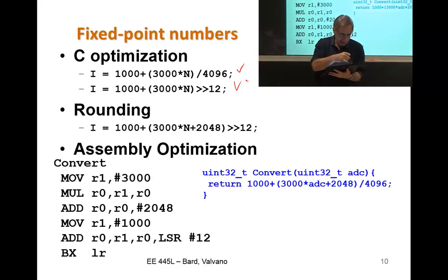Do you have to program in assembly language in this class? No. But we're going to look at assembly language in a couple of places. We're going to look at it for the issue of overflow, because it's not in C that the overflow happens. The overflow happens in assembly, so we'll make sure that when it multiplies, it's really doing a 32-bit multiply. When it does an add, we can see it's doing a 32-bit add.